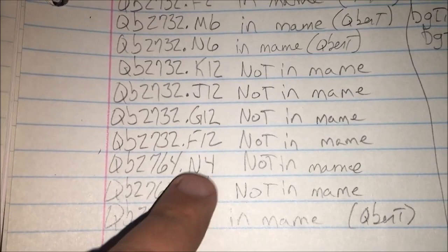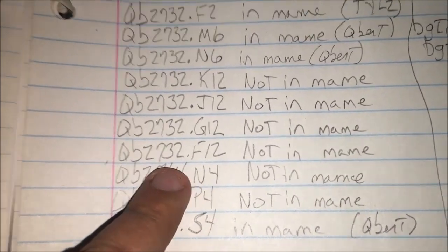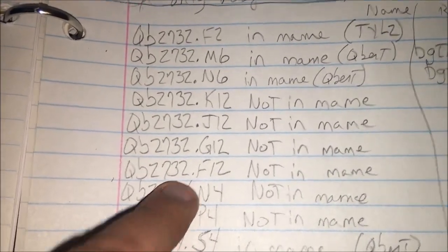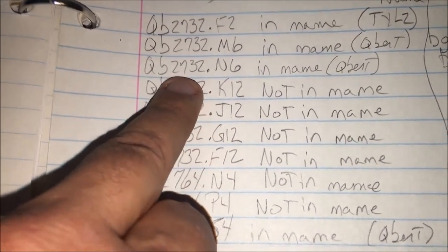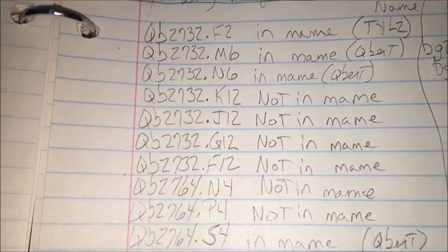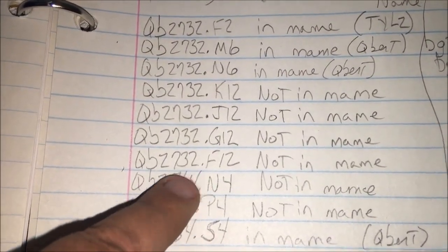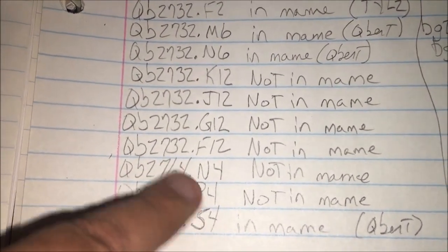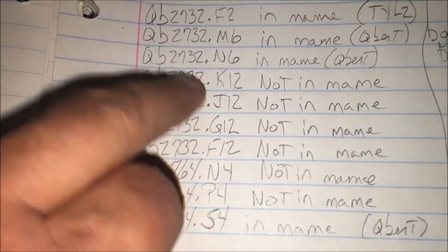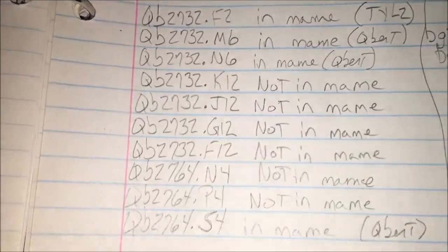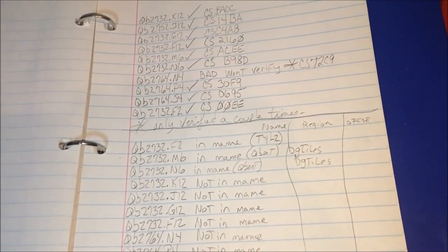So I'm going to burn Q*bert ROMs for the CPU, and I'm going to leave the sprite ROMs alone at first, because the game will run with bad sprite ROMs. It won't run with bad CPU ROMs. So I want to make sure that I have these, and then we'll look at these later on. I might have to burn new sprite ROMs, that's fine. But that's what I've done so far.